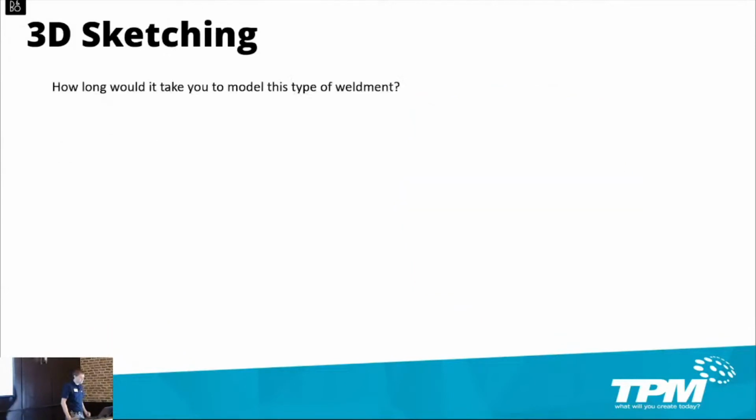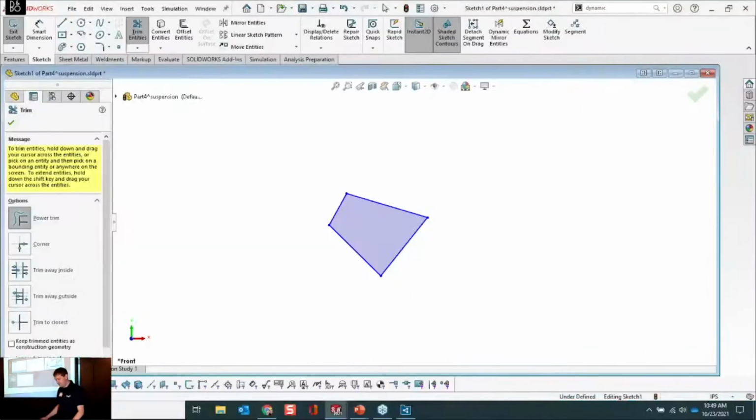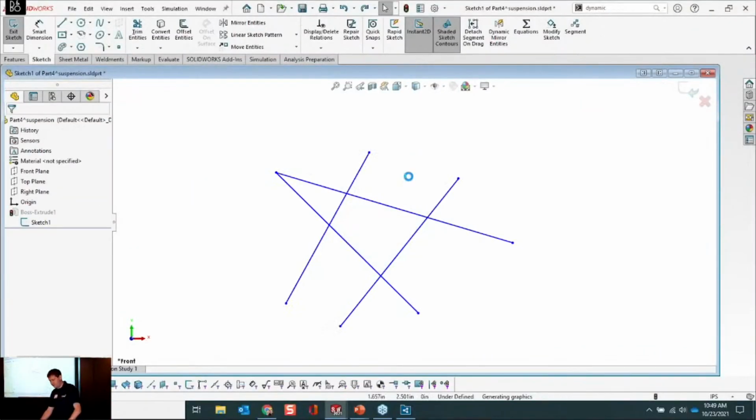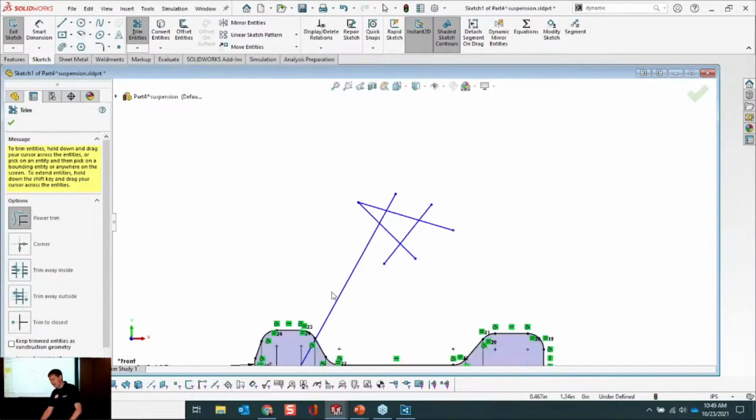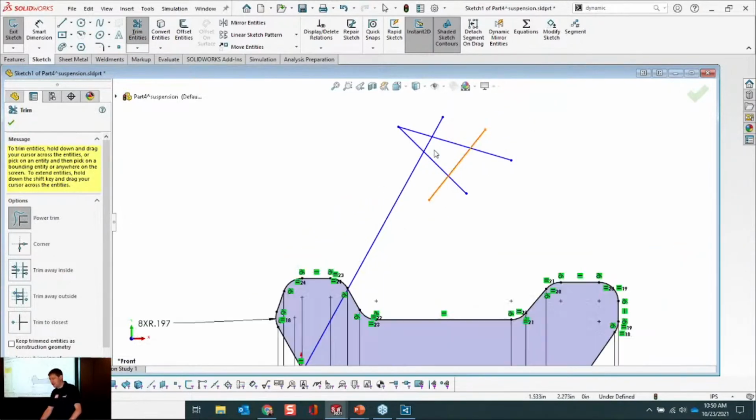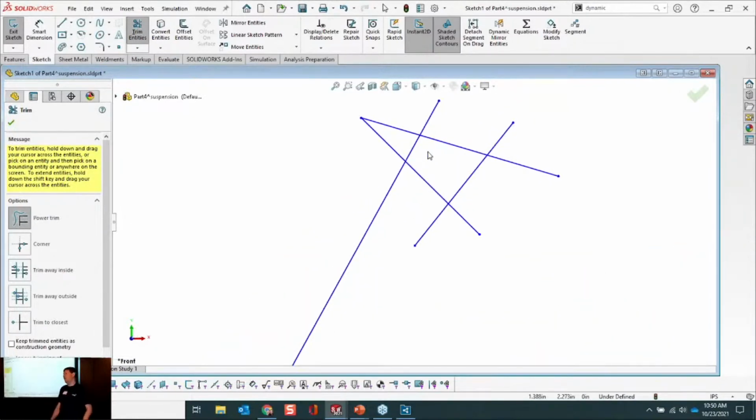You can connect lines together too. Say again? You can connect 2 lines together. With trim? Oh, yes, holding shift, you can extend the line too. So let's say you have a line here, hold shift. I extended that line out that way. It went to my near sketch entity there. But yeah, that's another one in there too, holding shift.